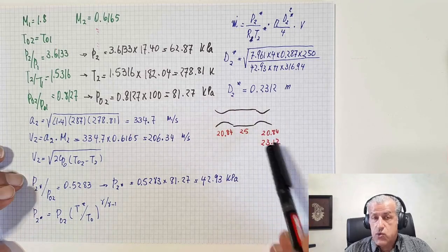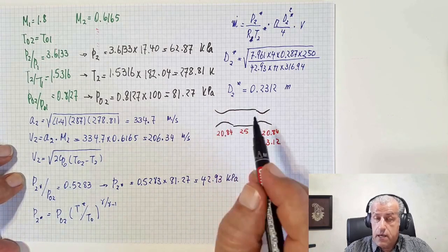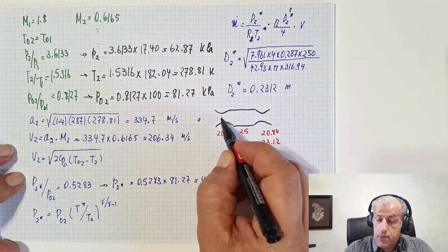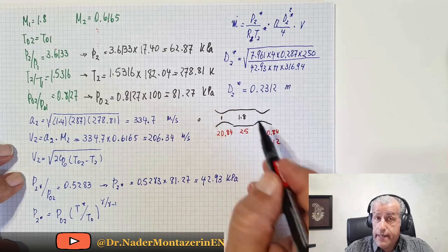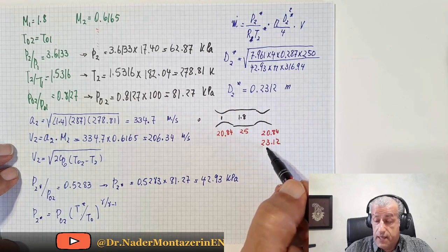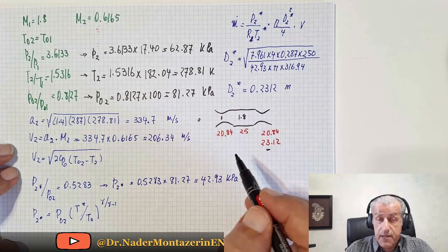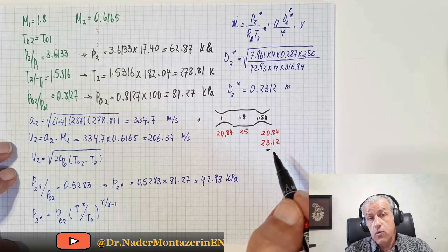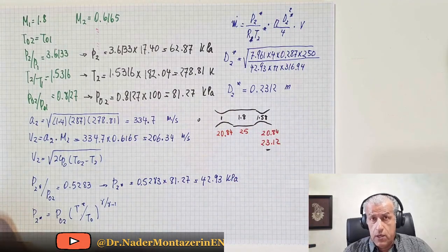And if this is 23.12, what we would learn is that the flow would start at 0, it comes to 1, it comes to 1.8, and if it goes isentropically through this throat, then the value of the Mach number at the second throat would be 1.58 and not 1. And therefore, you would have supersonic velocity throughout.